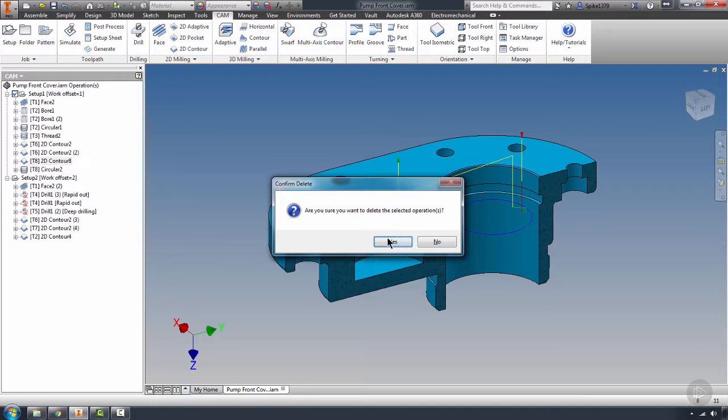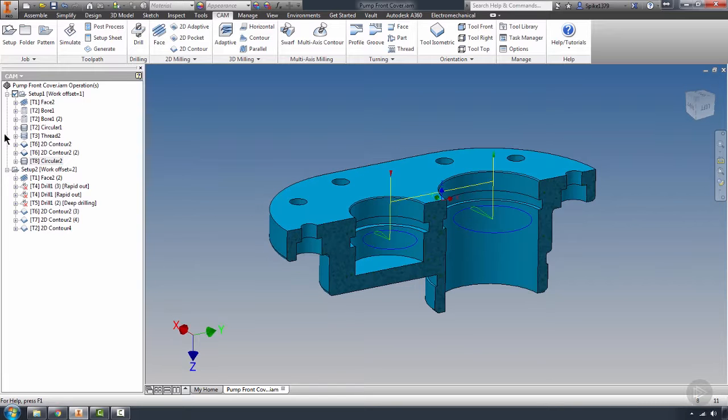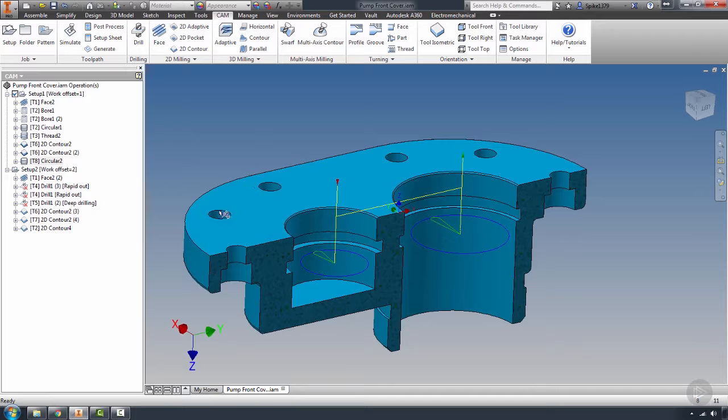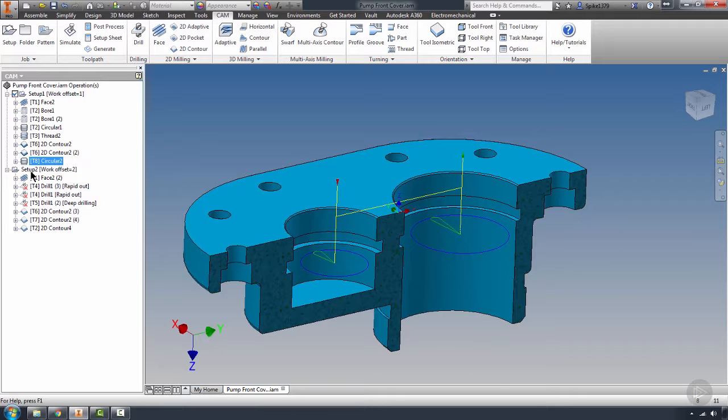The other side to the circular is that the posted code is going to force arc moves versus anything you may have set up within your post processor for odd contoured surfaces. So now that we've added that, we do want to have spot faces on the back side of this, and this is kind of unorthodox, but I would rather switch between the two operations here and do that.